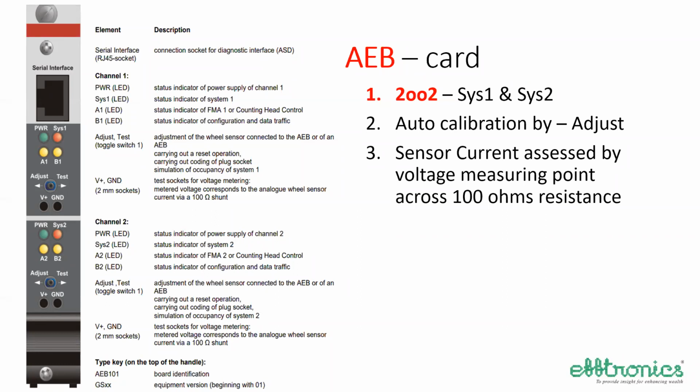But axle counting, or whatever we may call it, using sensors by the side of the track or on the track or rails, there is a lot of scope and research is going on. Some products are coming out. For example, precisely where the train is can be found out by burying optical fiber cable just a meter away from the track, and any wheel problem or rail problem can be found by sensing acoustic differences or vibrations. Even somebody walking by the side of the track can be detected like that. So the research is going on in that direction, and some products are coming out. Track circuit is on its way out, but still not completely, because it is such a simple system. It is more than 120 years old, but still.